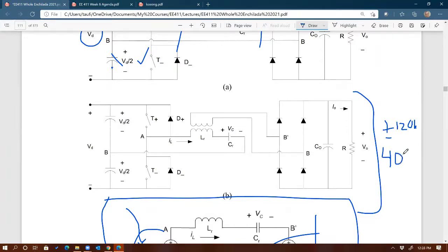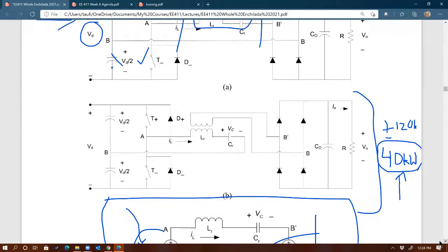The main reason is this. Imagine if you get 40 kilowatt from single phase. Can you imagine how much current would be required by a single phase for this? A lot, right? So that's why you need three phase. Okay. If single phase was, say, a higher voltage that was equivalent to the three-phase equivalent voltage, would it be the same amount of current, or does three-phase offer an advantage past that?